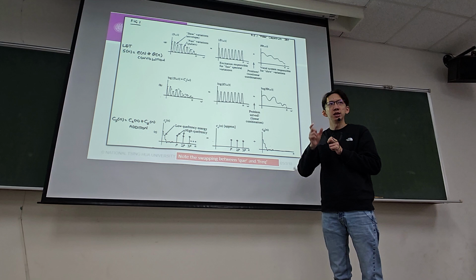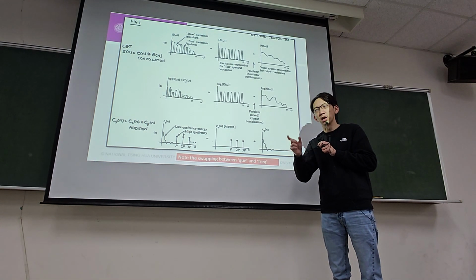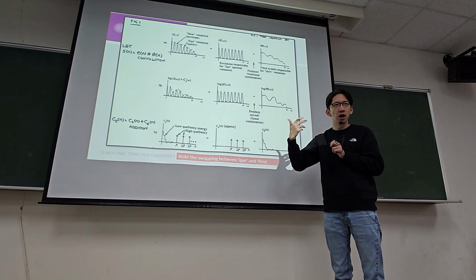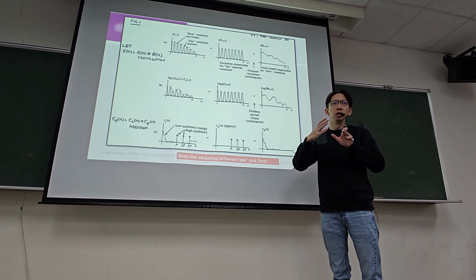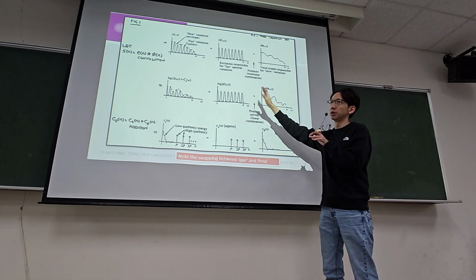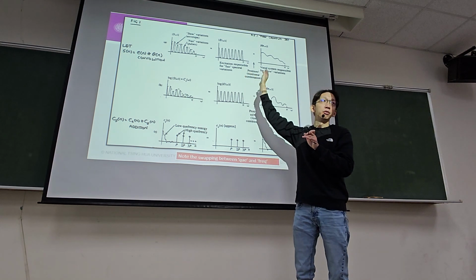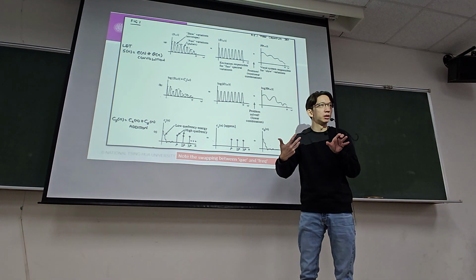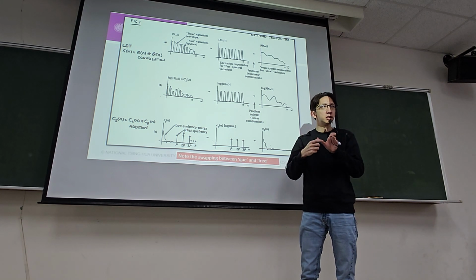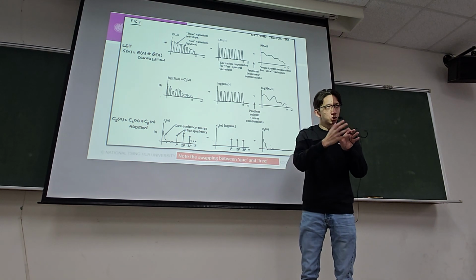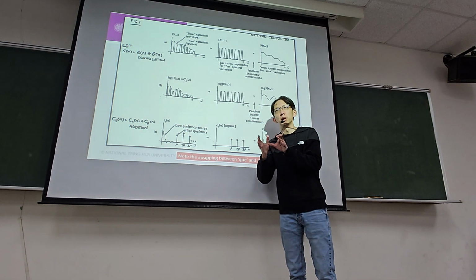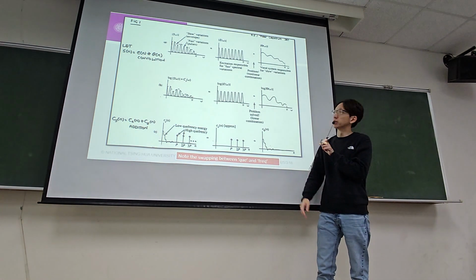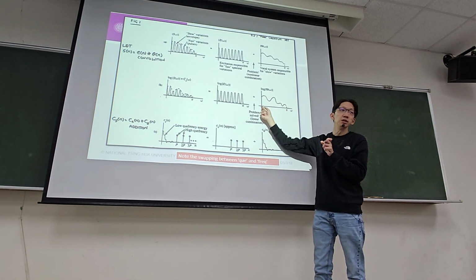Because of that source exciting filter concept, the cepstrum analysis makes sense, because it helps us tease apart the slowly varying formant structure and the highly varying fundamental frequency harmonic structure. These two things can become separate, so we can analyze this signal as though we're analyzing the source part or the filter part. Later on, for automatic speech recognition, what we really care about is the filter part.